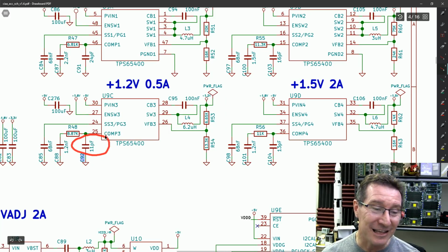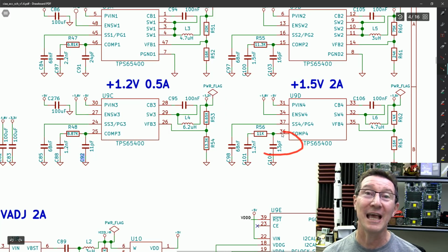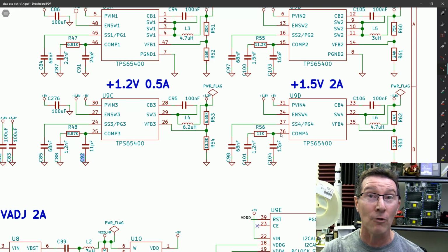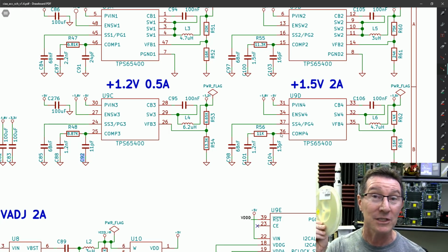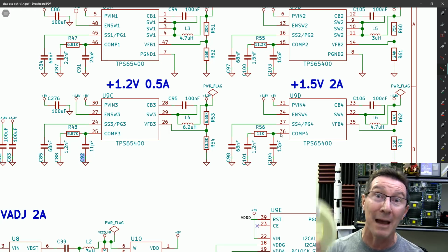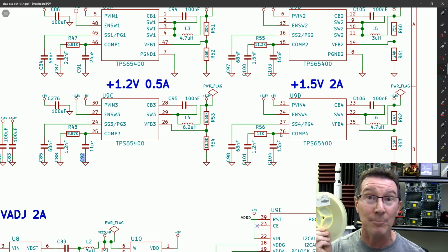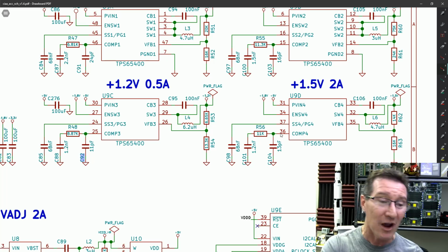You could easily consolidate these two values here, which are the only ones used in the design. It's the only place it's used, and you've got to go buy a whole reel. Then your purchasing officer has to go and purchase these from somewhere. You've got to find them in stock. They may not have them in stock. It could screw up your entire production schedule just because you decided you needed an 11 picofarad cap in there.